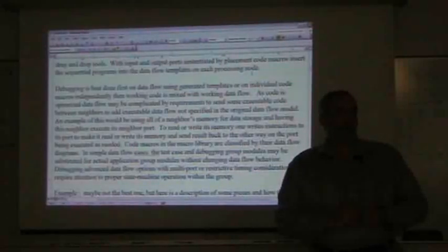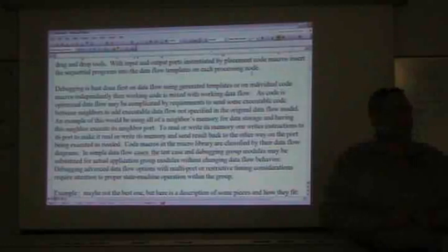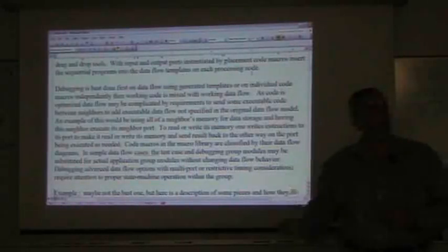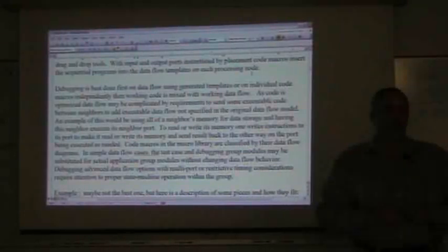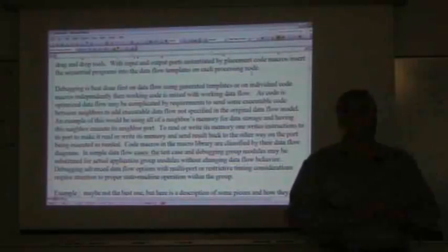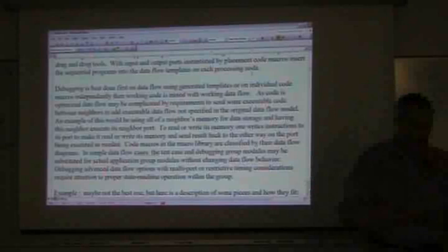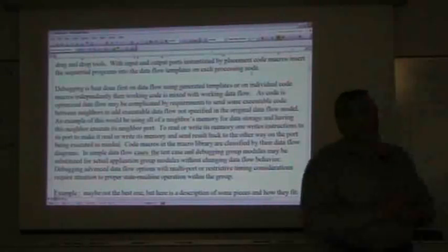In the case of analog, I set up an A to D node that's sampling at a given rate. The rate could be determined by the outside world, could be determined by another node. In this case, it's just being determined by internal timing. So that node is sampling the analog to digital converter. And the way our A to D works is that we have a voltage-controlled oscillator, and the voltage on the input will be proportional to the rate of oscillations. So you take multiple samples and you subtract, and you get a count, which tells you how fast that voltage-controlled oscillator is going, and it will follow the voltage on the pin.